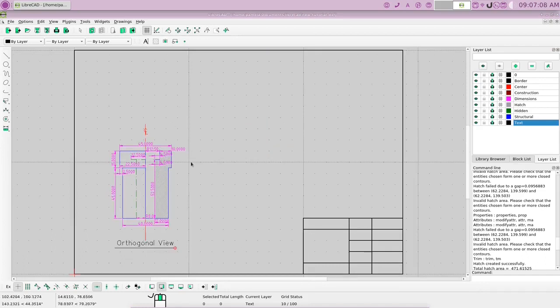Now it's difficult to see what's going on here unless we had a top view up here so that we could see the top of this unit. So we're going to draw a top view, and then we will actually be able to see what is happening in these hidden lines more clearly. Okay, so let's get ready for the top. Okay, to draw a top view, we're going to use some of the lines we have here. And to see them clearly, let's actually get rid of some of these things like the dimensions by turning them off. Just go to the little eye here and turn off the dimensions.